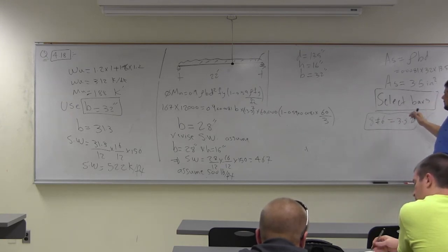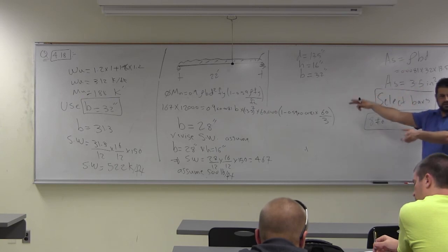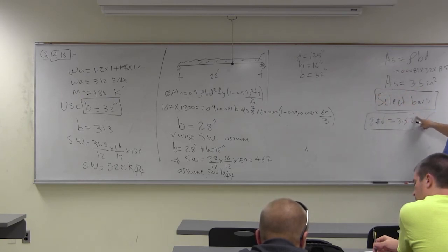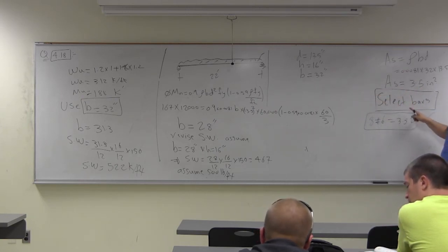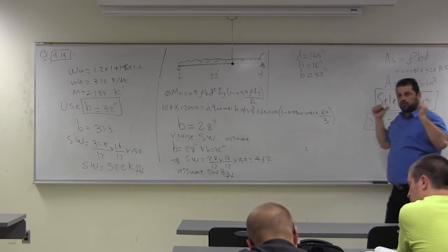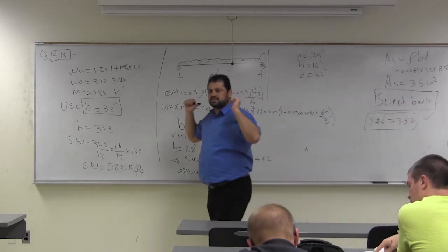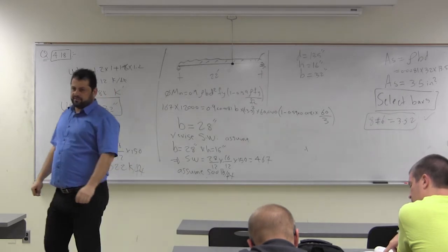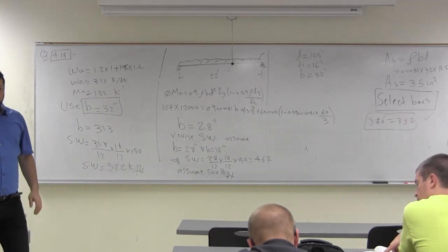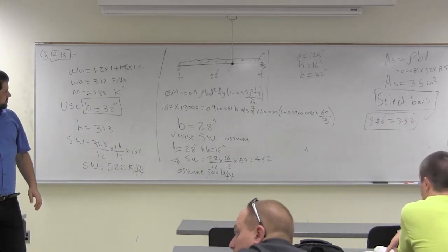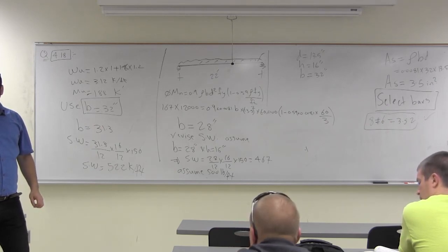So that's what we have. And now you can go back and calculate VMN a little bit more because of this. And our row, we kept it at around 0.6, row 0.005. Right. So we're using our H as 16 inches. Yes. And then there's a 2-inch gap, right, before any of the... 2.5 to the center of the steel.